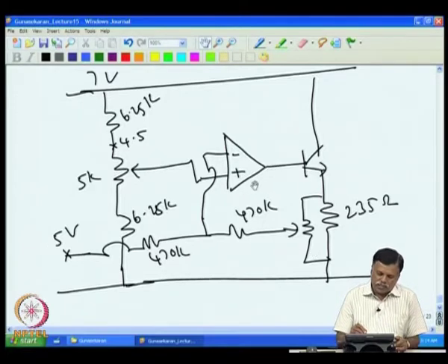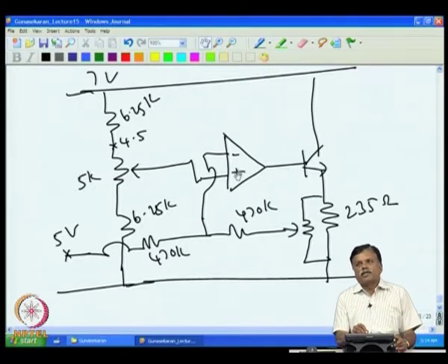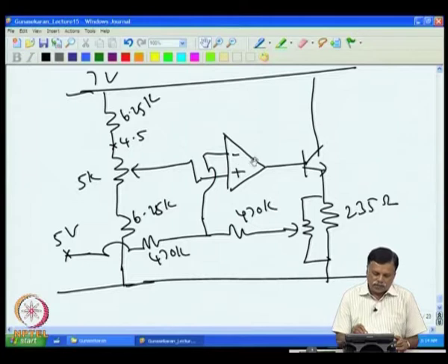The offset voltage change, for example, if I take the same general purpose op amp, we can expect it is 15 microvolt per degree C. So, for 100 degree C, we can say 1.5 millivolt change is expected here. If 1.5 millivolt change here, then they also have to change 1.5 millivolt here.